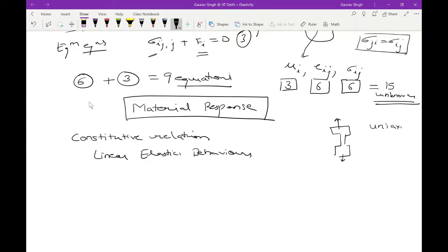So it's a uniaxial test, and then you would eventually want to plot the relationship between uniaxial stress and strain. I do not want to discuss this a lot, but you must be aware that there is a proportional limit at which the initial linear response between strain and stress ends.